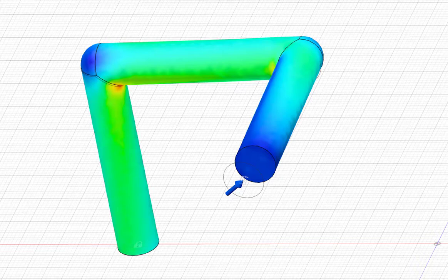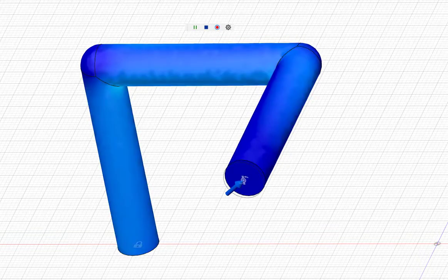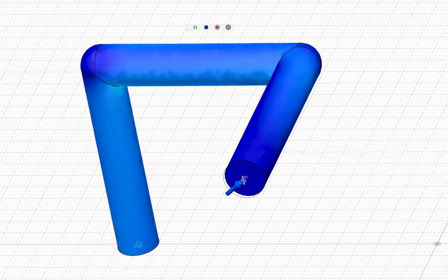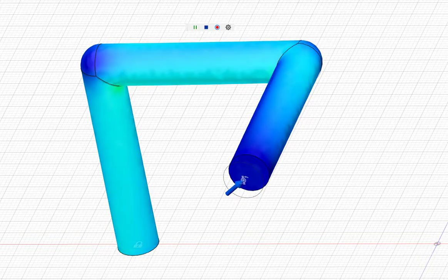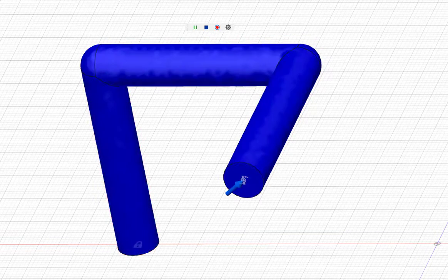Or we could use something called Castigliano's theorem to sort that out. So what does that deformation look like? Here's an example of what it would do. And I'm telling you right now that with Castigliano's theorem, you could write a closed form solution that would match the deflection that the FEA is generating. So let's get to it.